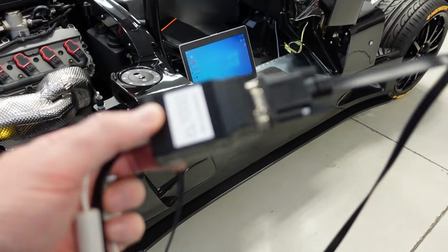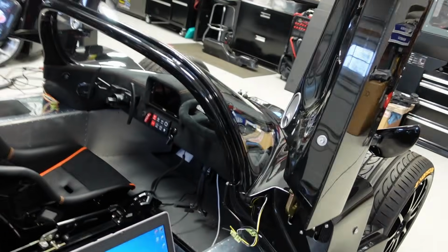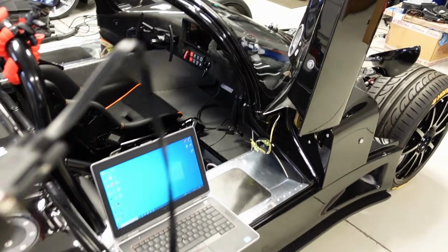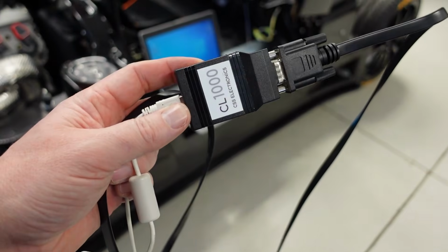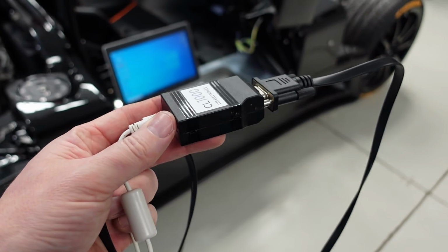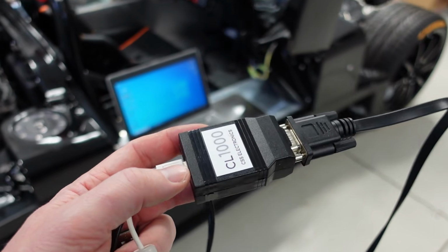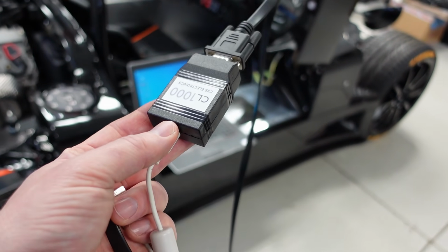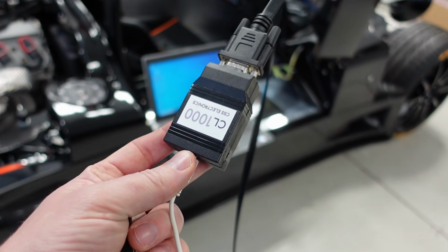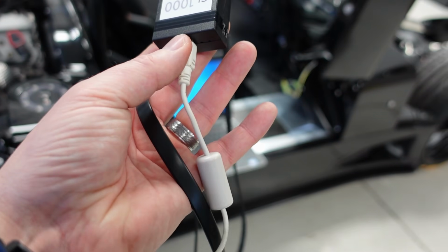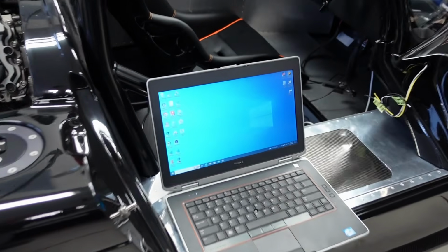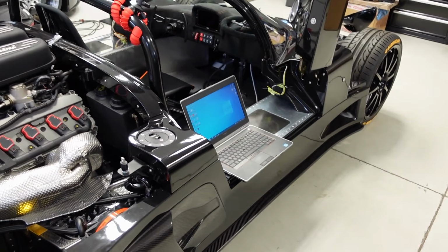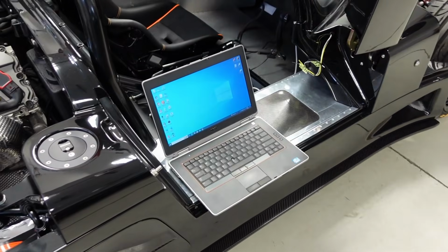As soon as we plug this in to the OBD2 port underneath the dash, and once it senses the CAN bus operational, this is going to start recording. So this is kind of a headless recording device. However, after you plug it in, after it senses there's CAN bus operational, you plug it into your laptop, and then that makes it a live feed directly into the SavvyCAN software, which I'm going to show you as well. Then I can monitor the CAN bus live.